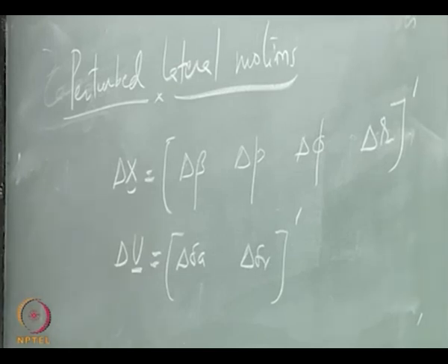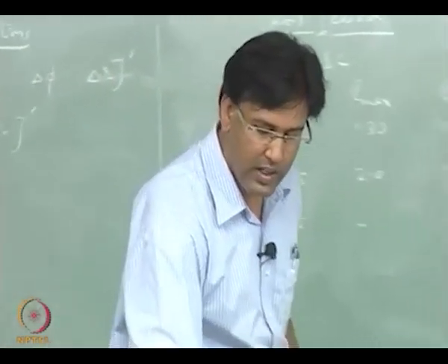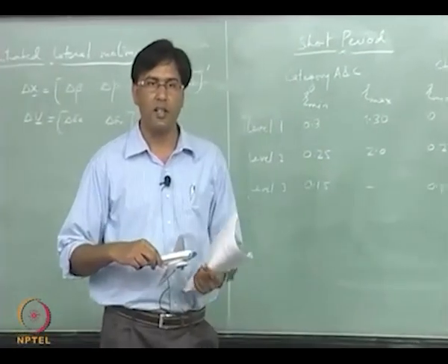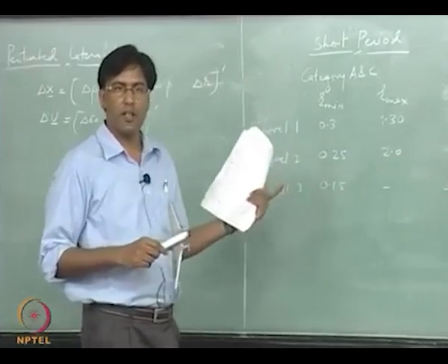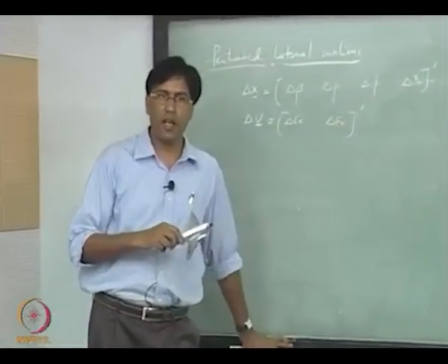So we are looking at longitudinal and non longitudinal dynamics as completely decoupled, and that will happen only in this particular flying condition. If you are talking about let us say level turn, then it may not be decoupled, right.